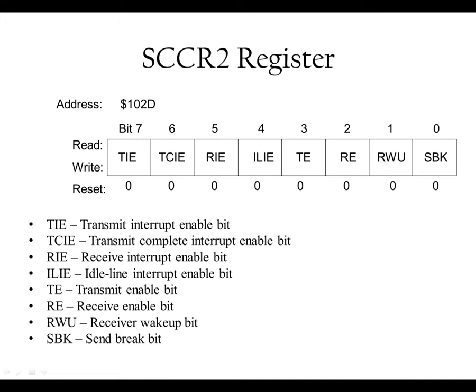But the interesting part is, just like any other memory location, you can use it as a memory location, and if you are trying to save something into this location, you will end up saving into the register. You see what I'm saying? So that makes our job easy, because you will be using the same instructions that you used before, like LDAA or STAA, to save things here.